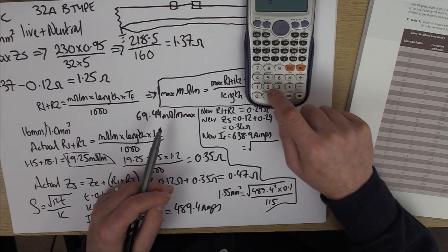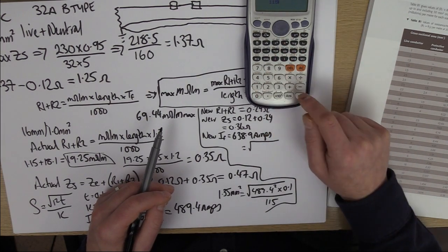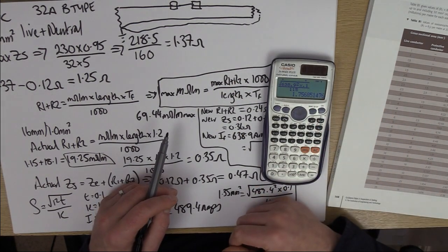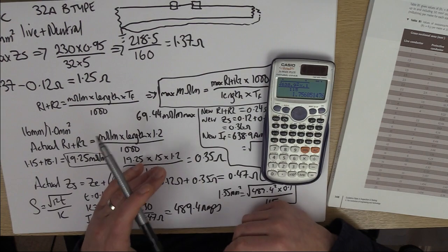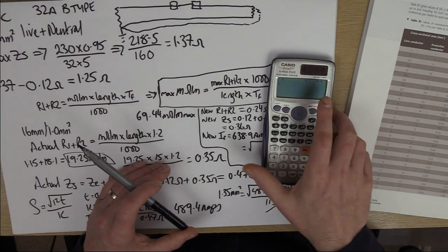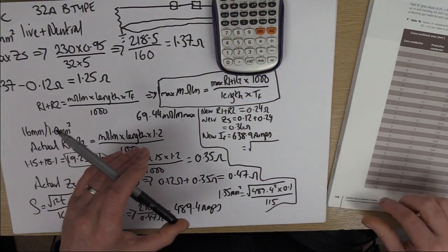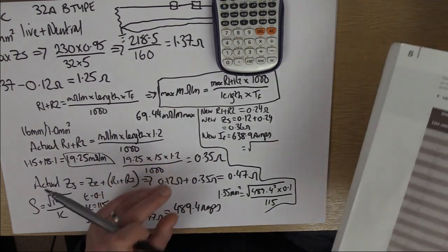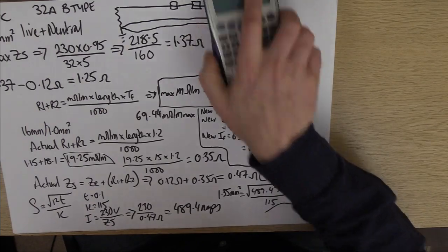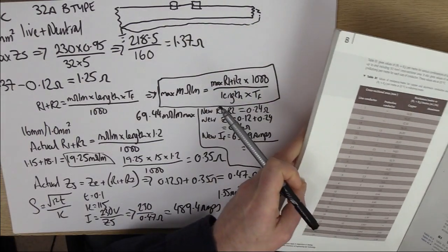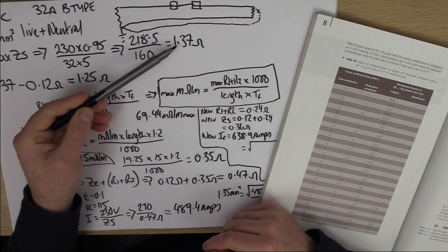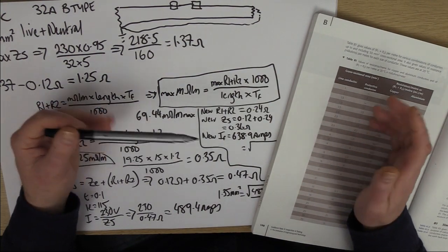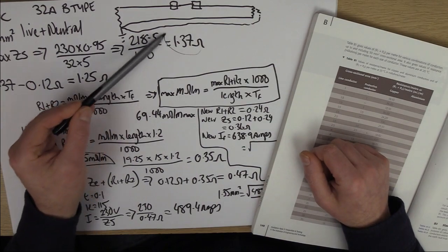638.9 squared times 0.1 over 115. So now it's saying minimum's 1.75, so the 1.5 doesn't work. Oh no. So should we just jump to a more sensible option? And this is a great example of where the Zs might comply, but your adiabatic doesn't. So you can't just go by this all the time.